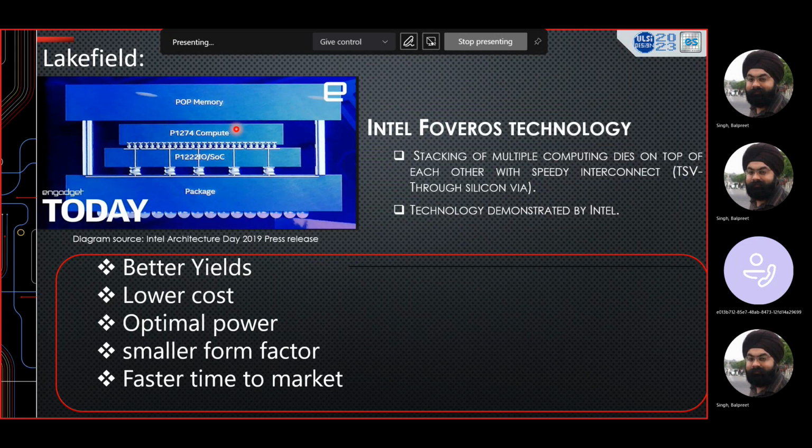Good question. So a microbump typically is a very small patch of copper, 9 micron, 10 micron, 20 micron radius. The resistance of that is a couple of milliohms. Now, when you draw a typical metal from one transistor driving the other transistor, the resistance is of the order of kilo ohms. And the microbump is only 5 to 6 milliohms in that range. So it's very insignificant in impacting any of your performance. And this is a ballpark number I'm talking about, not any technology number.